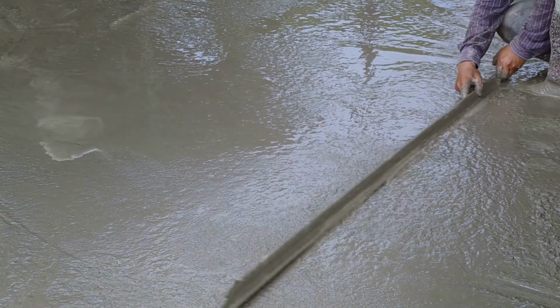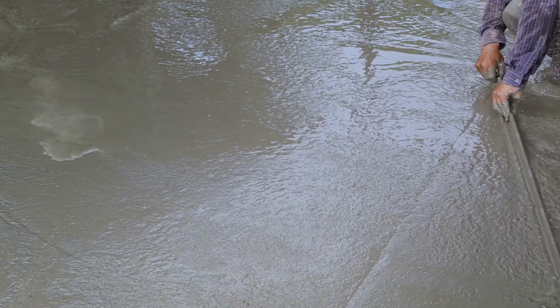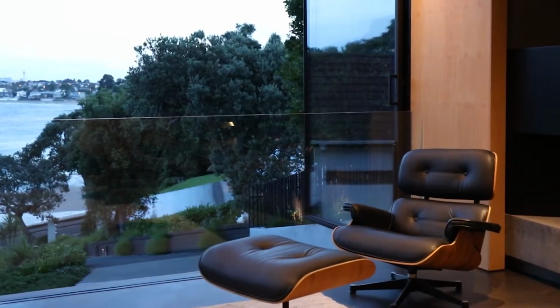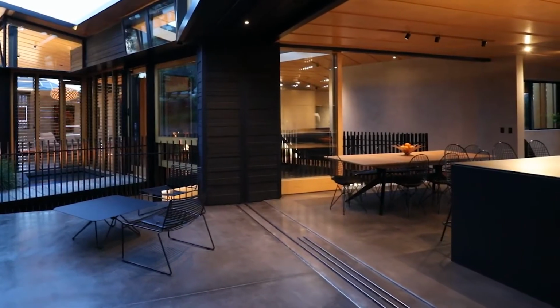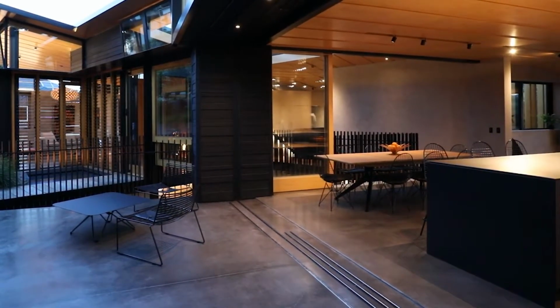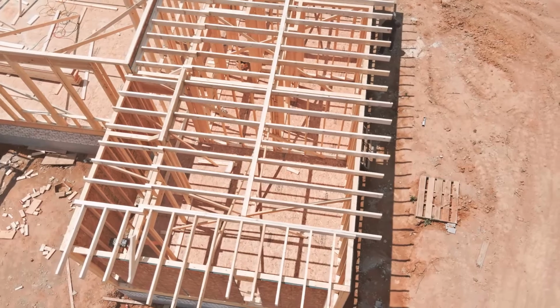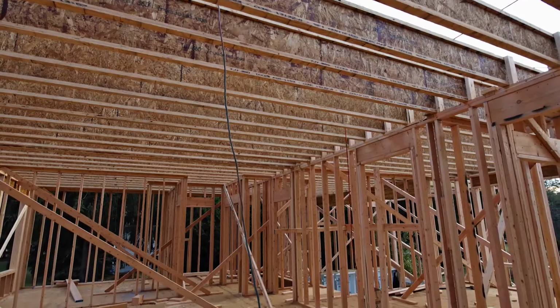Bear in mind, when programming the build, these sorts of concretes can require a longer curing time. Also remember, the concrete slab should be exposed and adjacent to large, north-facing windows to make use of its thermal mass during wintertime. Suspended timber has lower embodied carbon, but a higher cost.